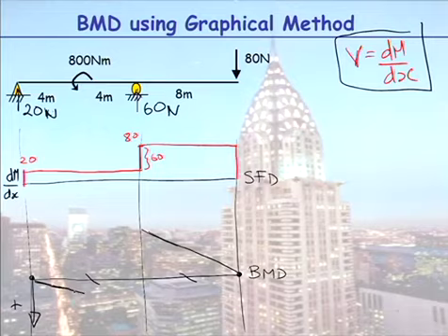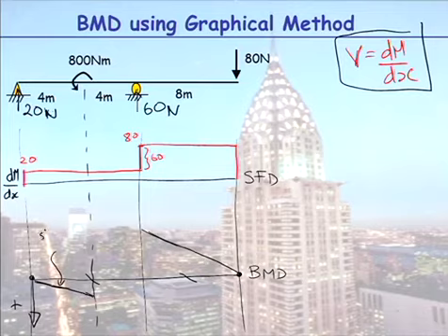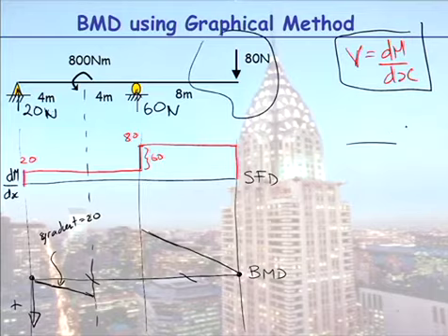Now, again, I'm a bit confused as to what to do with the applied bending moment, but I know it affects my diagram. So I'll just take my sloping line, I'll call it the gradient, and I'll just take it up to that moment value. Now, the other way to look at this is, how did I get that linear line there? I can cut the beam.